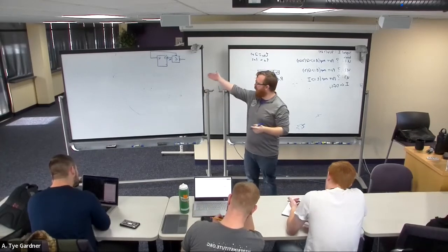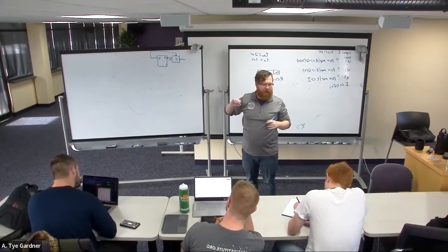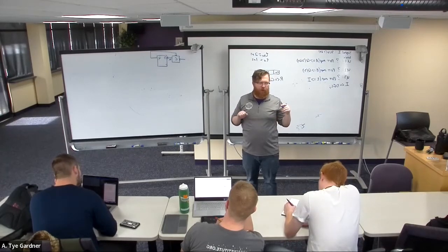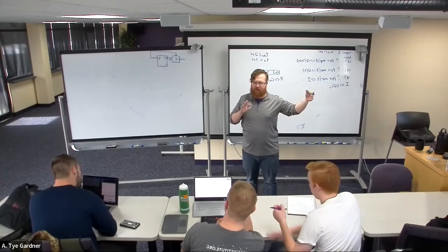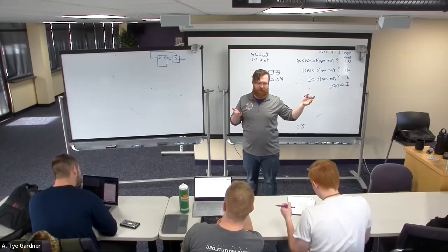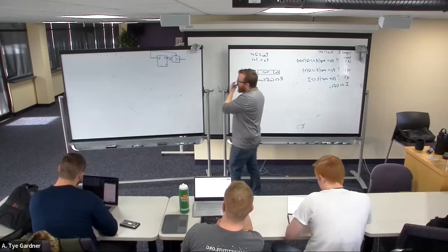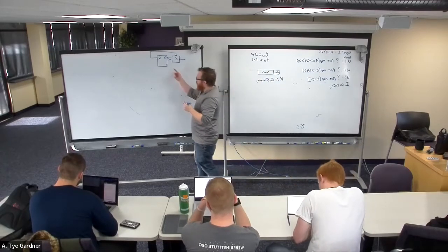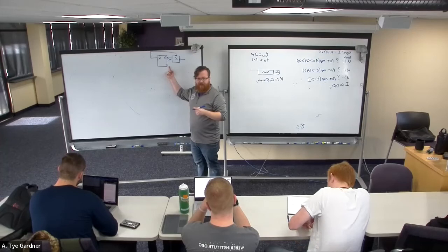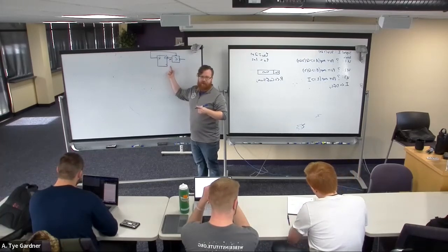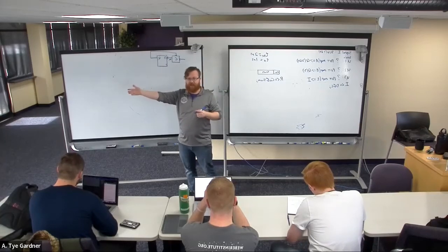Because we're going to design that combinational logic probably with a K-map, because that's what we do the most of. And K-maps tend to end up with a 2 or 3 level of gates, right? 2 if there's no inverts, 3 if there is an invert. And if the clock starts going really fast, then there's not enough time for this combinational logic to update alpha before the next rising edge happens.